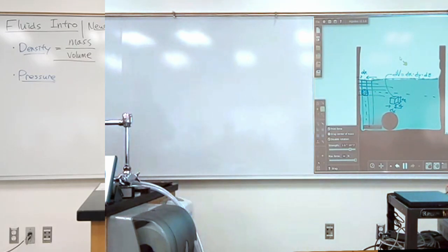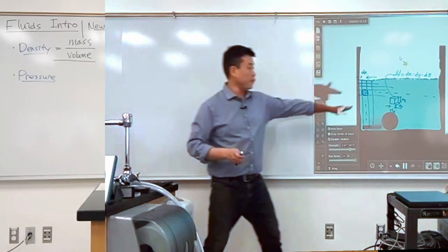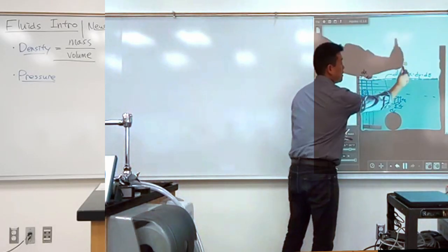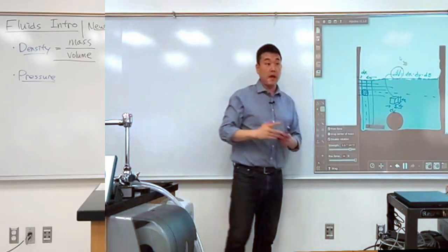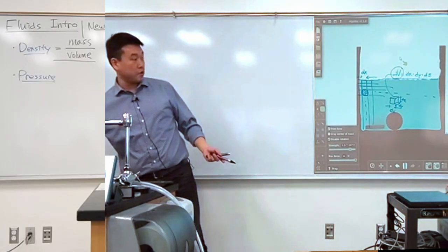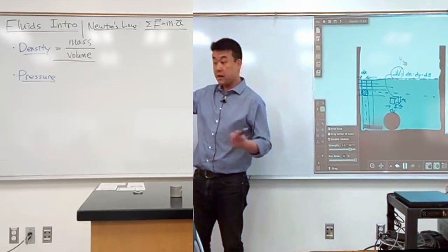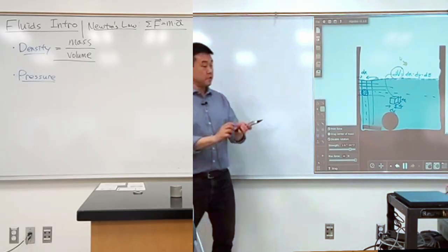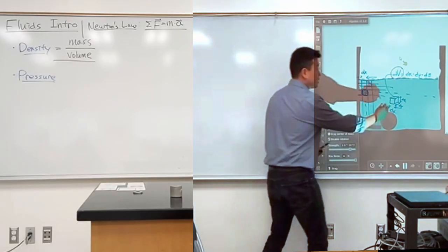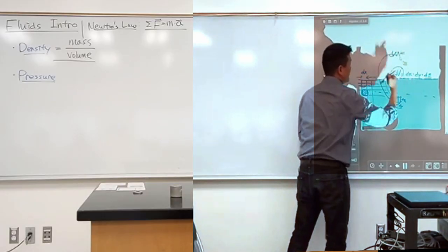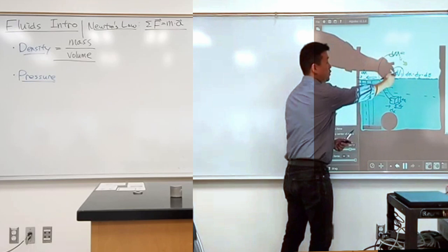So, you are going to parameterize the fluid element so that you are describing it in terms of this volume element. And when you try to describe the mechanics of it, you are going to need to know the actual mass of that element. And the way to describe the mass would be that small amount of mass for this element is the density times the volume element.